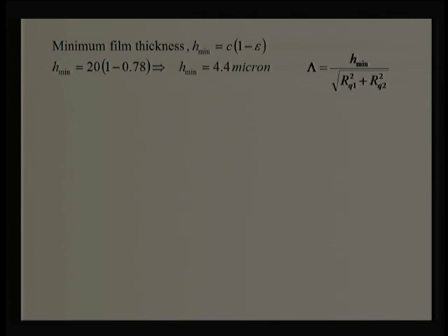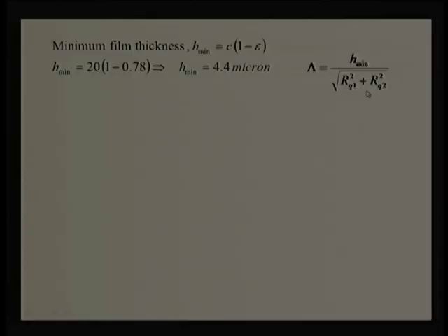We are talking about hydrodynamic lubrication, and we know hydrodynamic lubrication will be valid for the specific film thickness by and large more than 5. If surface roughnesses of shaft and bearing surfaces are provided to us, we can find out the specific film thickness using this relation, that will be the ratio of minimum film thickness to the composite surface roughness.